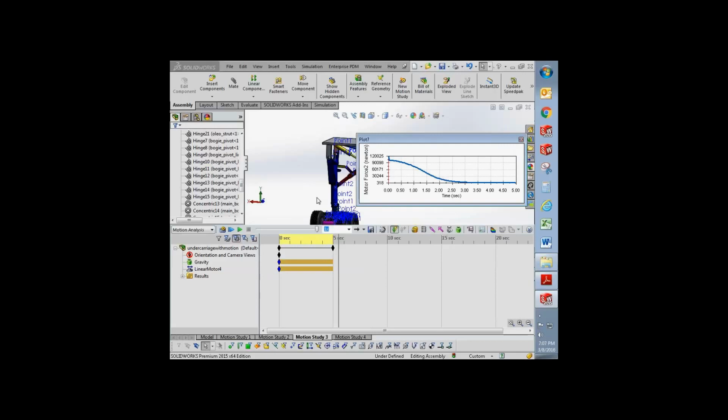So any questions? This is the general procedure I'm going to use to solve any motion. It's going to use your mates. It's going to use your part geometry. We only support solids, so no surfaces, because we need the mass and inertia. Yes, go ahead. So to get the results there, you could have all the material properties. Right. Yeah, so it grabs all that from the SolidWorks that we are talking about. We already have that defined there, and for those mass properties, also.